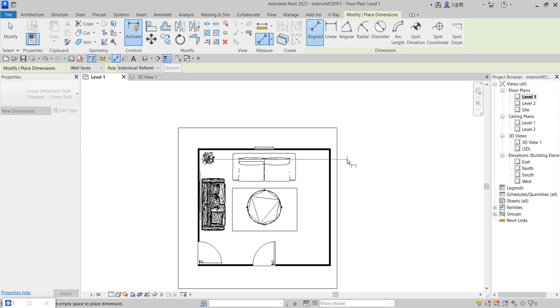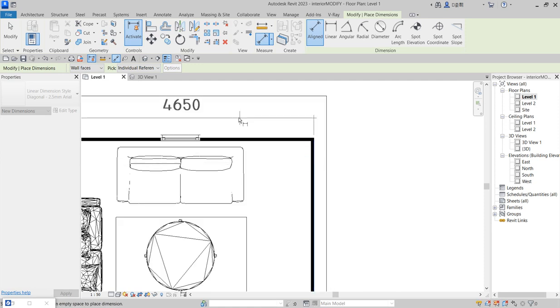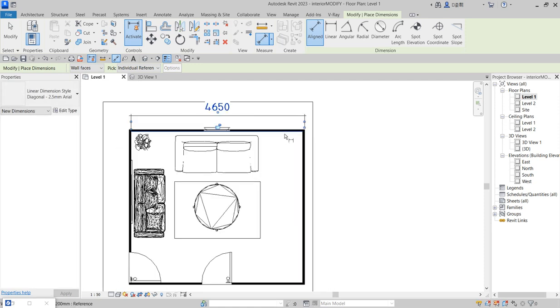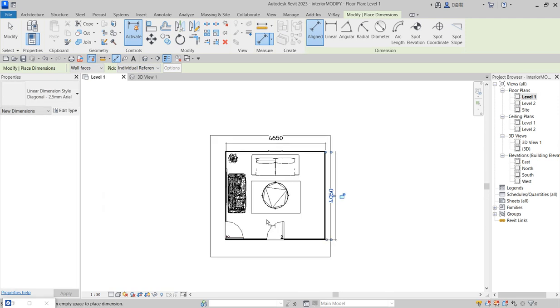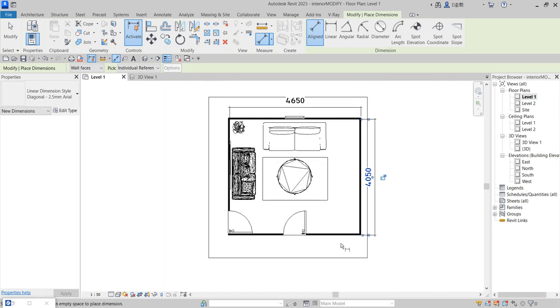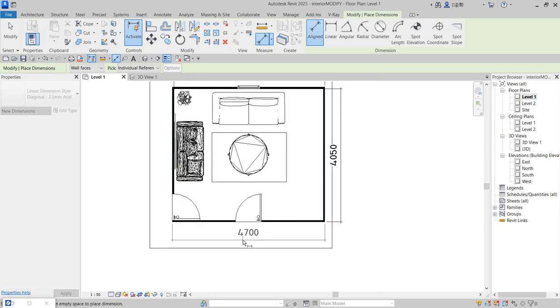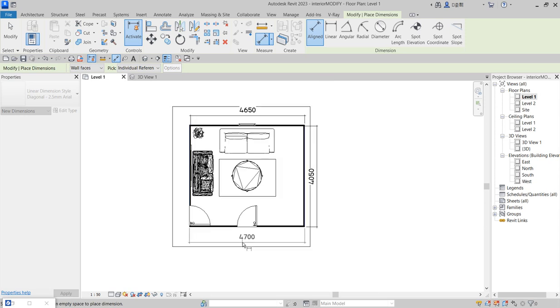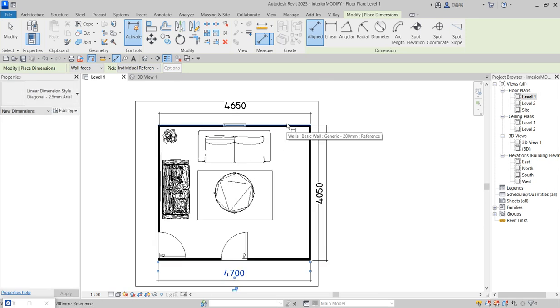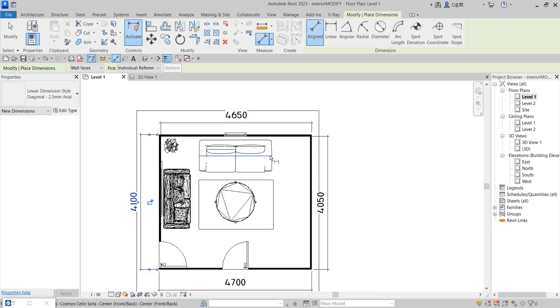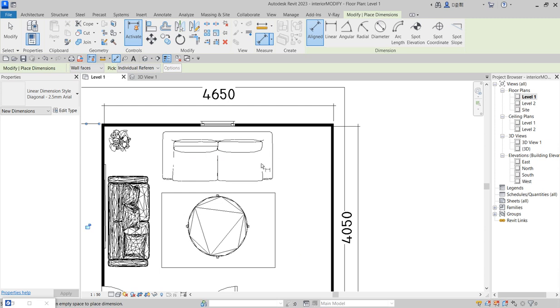So for them to calculate the material and know the size of everything, this is the dimension. The first side dimensions are very much needed, so you take it like that. The space is limited, and because some walls are not permanently fixed, you need to check them out, like this one now. So this is out to out, so you need to take that as well. You take out to out dimension and in to in dimension.